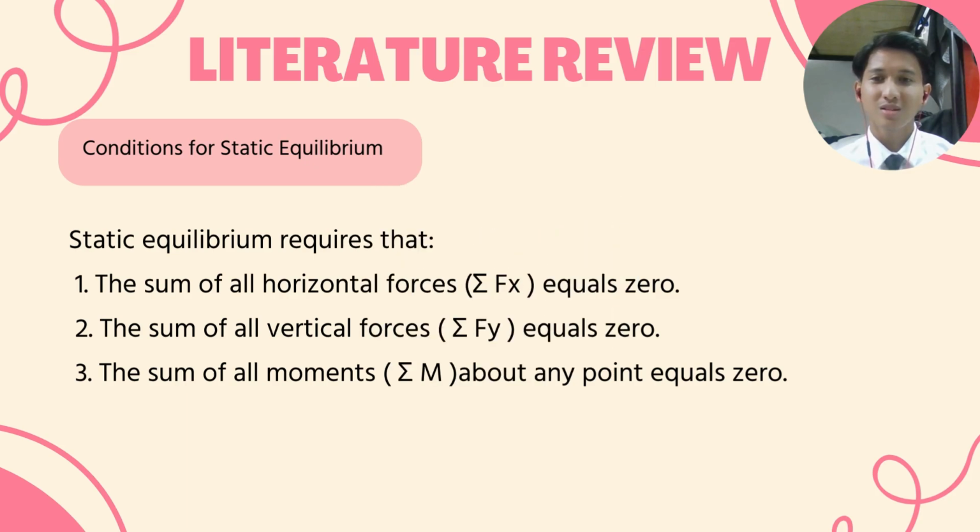For the second subtopic, the conditions for static equilibrium. Static equilibrium requires three things. The first is that the sum of all horizontal forces, Fx, equals 0. The second is that the sum of all vertical forces, Fy, equals 0. And the sum of all moments, M, about any point also equals 0. All three are equal to 0.